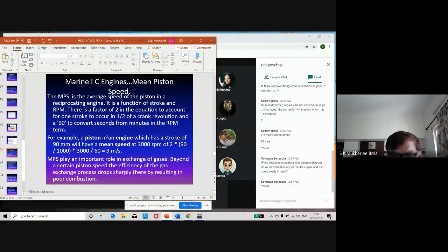So what I told you, the forces involved in accelerating and decelerating the piston are massive. And the ultimate load goes on the bearing which is holding that piston, isn't it? So the bearing has to take a lot of load. It is not only load for rotating power. It is the forces involved in the moving masses, the inertia forces. I expect you understand what it means.